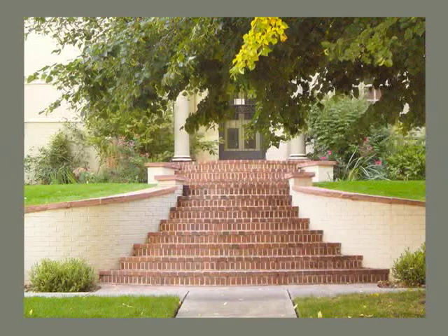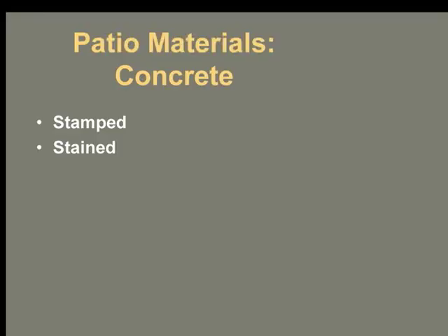I wish they had used a sand set or an adhesive on those treads because I think there's too many mortar joints. It's too busy looking, and it's going to be more maintenance. But they are cool stairs. They're all perfectly radiused.